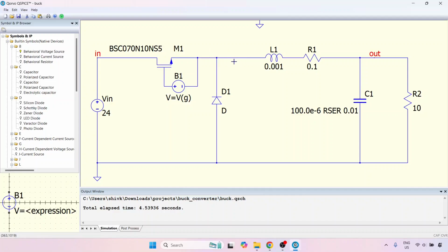And that is why the voltage at this point will be a switched voltage, which means you can never produce, just with your power electronic device, exactly the voltage you want. You will only be able to produce a switched voltage which comes close to your output voltage. The rest of it has to be done through the action of filters. And that is where pulse width modulation comes in, by combining your low frequency signal with a high frequency carrier waveform. You can use filter components which are not too bulky in order to remove the switching frequency harmonics and produce your necessary output voltage.